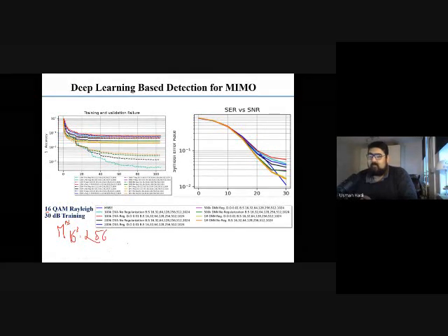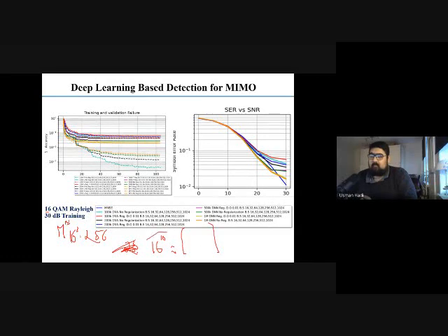Now, if you have 256 QAM, or let's say not 256, but you keep it simple as 16 QAM, and you have 10 RX receiver antennas, just imagine what this number will be. That will become a very huge number. And that is the limitation of the system: the output depends on m to the power of n, and n is NR, the number of receiver antennas.